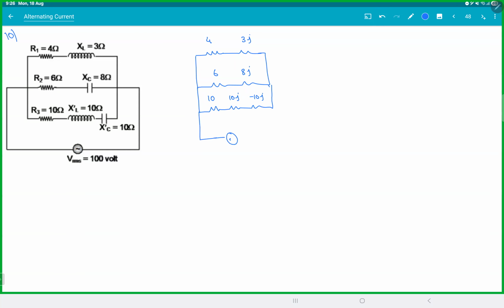And again, that is your RMS value. So V bar is 100 root 2, 0 degrees. So Z1 bar is 4 plus 3J, that is 5, at 3 by 4, 37 degrees. Z2 bar is 10, 53 degrees. Z3 bar is actually 10, 0. Is that clear what I did?